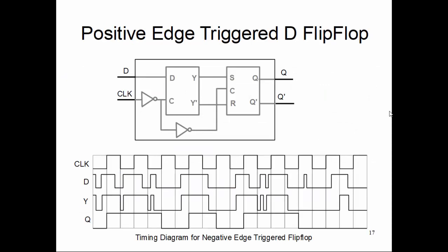The answer to that question with this configuration, this logic circuit, is we don't know. It can be either 1 or 0 depending on what's going on at that instance, right? It depends on the ambient temperature, humidity, this and that. A lot of factors go into that. It will go and be there at some point, hopefully staying at 0 or 1. We don't know, or it may even start oscillating, just going between 0 and 1, 0 and 1.